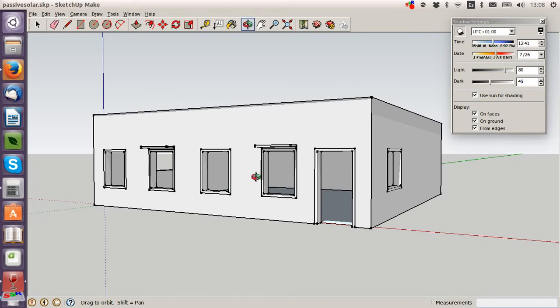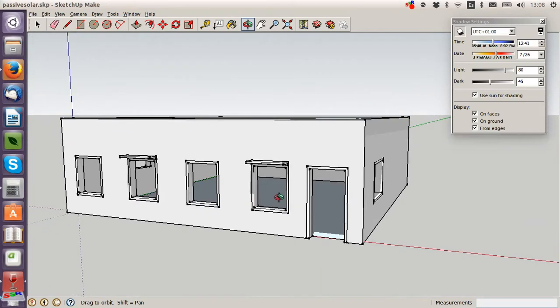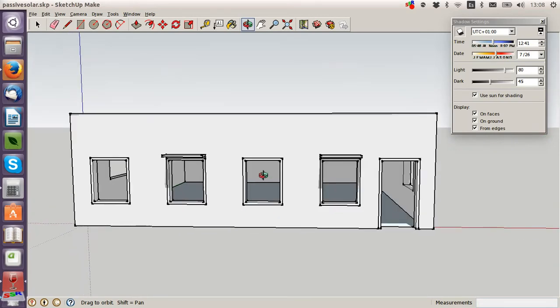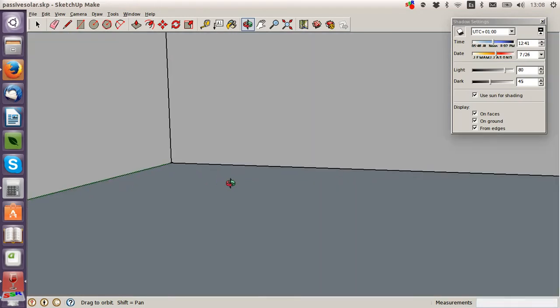Now you might think, well, isn't bigger better because I'm letting more sun in, so it will heat? Yes, in theory, because you let lots of heat in. What happens is that you get overheating. It's too hot in the day, and glass also loses quite a lot of temperature. Even the new insulated windows lose quite a lot. So you will get big temperature spikes, where in the day it's very hot in there, almost too hot, and at night the temperature goes down very quickly because we're losing a lot of heat through the windows. So this 7% rule is very easy to follow, and generally it's known that this works well.